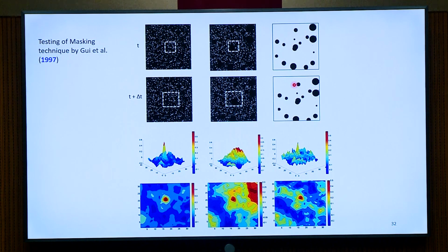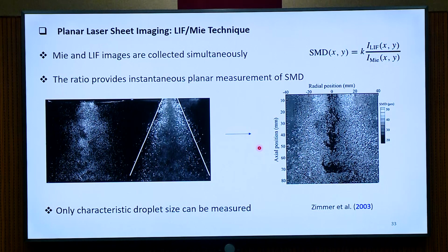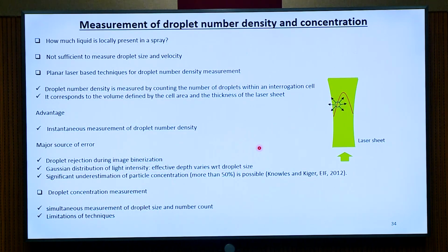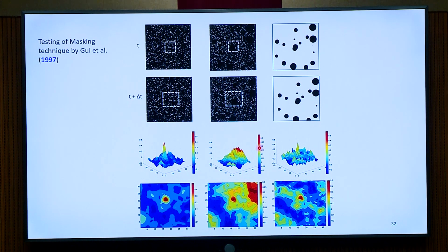So basically you imagine you have a conventional PIV image, but some empty spaces within that. If that is the case, that affects the image processing or the cross correlation. So the cross correlation will be lost because of this. So here you see that the peak is gone. So in order to overcome this, people have used some masking algorithm. I'm not going into detail. But if you use the masking algorithm, again the peak can appear. However, still it remains as a challenge.